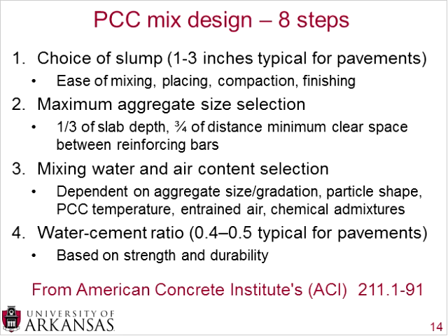After you've determined the maximum aggregate size, you determine the mixing water and air content selection. And this is also dependent on a variety of factors, including your aggregate size and your gradation. Aggregate size was chosen in step 2, but gradation could be chosen based on ease of local materials. Also the particle shape, the PCC temperature, whether or not you have entrained air, and of course chemical admixtures.